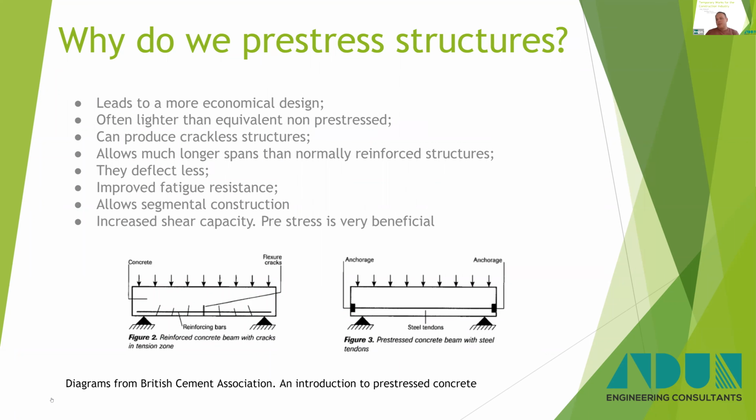Now, what I mean by this is you can design a structure so it remains in compression throughout its entire loading cycle. That is a significant benefit with reinforced concrete construction because it's cracks that allow moisture and therefore allow rusting of reinforcing parts. Whereas if it's pre-stressed or post-tensioned or pre-tensioned, you can stop it cracking under all loading conditions and therefore improve the durability of the structure.